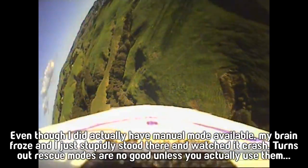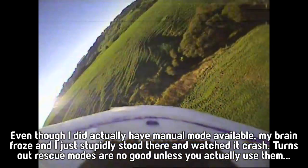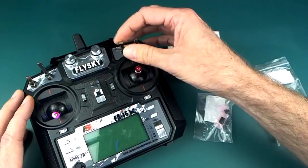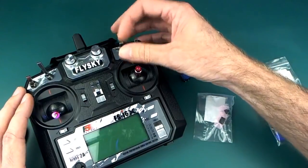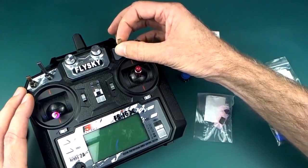And I was in fly-by-wire A, and fly-by-wire A didn't know how to get out of the tip stall, and obviously return to home wouldn't have been much better, I don't think. Anyway, so I'll have one position for manual, and then another position for return to home, and I always like to have it anyway, just in case it goes out of sight and behind a tree or something, and I'm like, oh shit, I can't see it, so I'll just use return to home to make it come back.